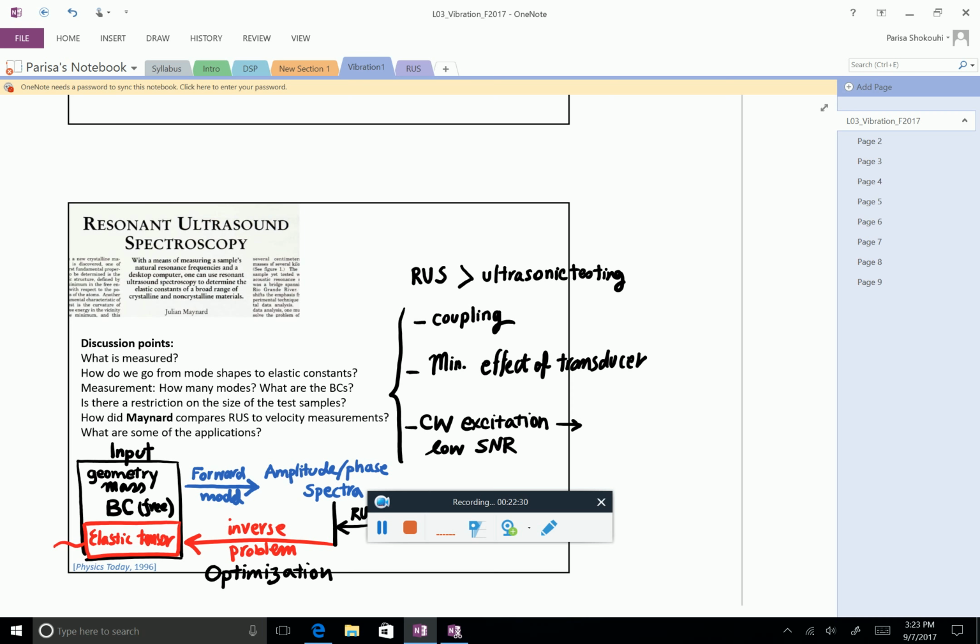So from 81, let's say if we write it in the Einstein notation, it's easy to go to 36, I think. Because let's say in engineering terms, sigma 1, 2 and 2, 1 are the same. 1, 1 and 1, 1 is the same. So there are certain symmetries that we have.